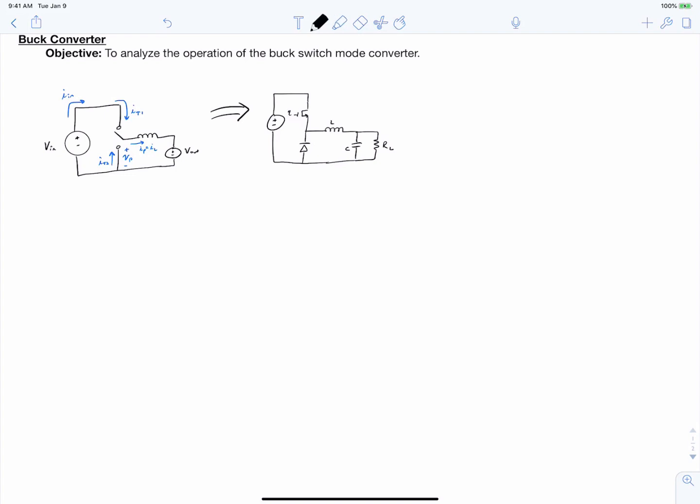So when you operate this converter, it takes one of two states depending on whether the MOSFET or diode are conducting. We'll sketch those states now. The first state is when the MOSFET is conducting, and at this point our entire input voltage is directly applied to our inductor plus our output voltage.